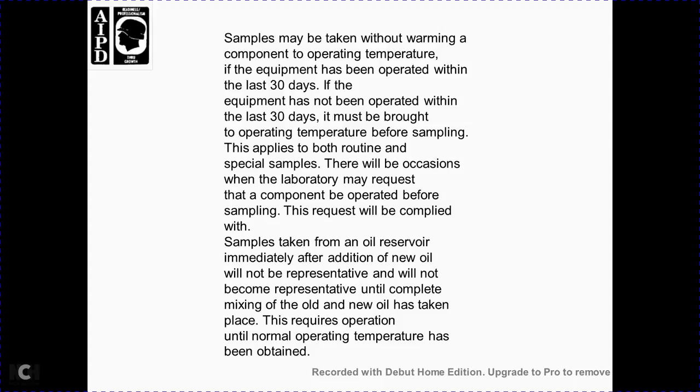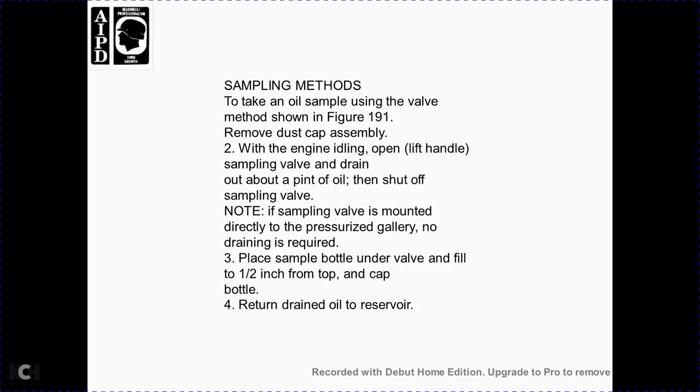Samples may be taken if the equipment has been operated within the last 30 days. If the equipment has not been operated within the last 30 days, it should be brought up to operating temperature before sampling. This applies to both routine and special samples, because the laboratory will require the component to have operated before the sample request will be complied with. Do not take the sample from the oil reservoir immediately after addition of new oil; new oil will not become representative until complete mixing with the old oil has taken place, which requires operation until normal operating temperature has been attained.